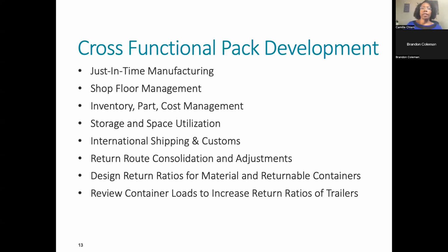Also, packaging comes into play when you're looking at international shipping and customs. The way you would pack something for an international shipment that's going to go on a sea container is going to be totally different than if you're shipping something by air across the world in a short time frame. You have totally different supply chains, totally different packs. If you're shipping by sea, by ocean, and it's a part that could rust, then you need to protect for moisture, because there will be moisture in the sea containers.